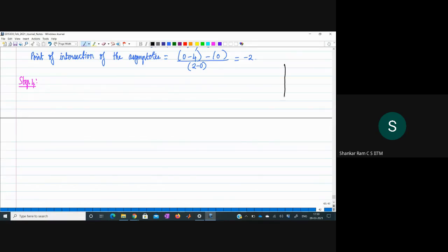Let me explain, by plotting the S-plane for our particular example. If we plot the two open loop poles, in our particular example, one branch from minus 4 will start like this, and another branch from 0 will start like this. How can I be sure that this is how the branch from minus 4 and 0 will start?